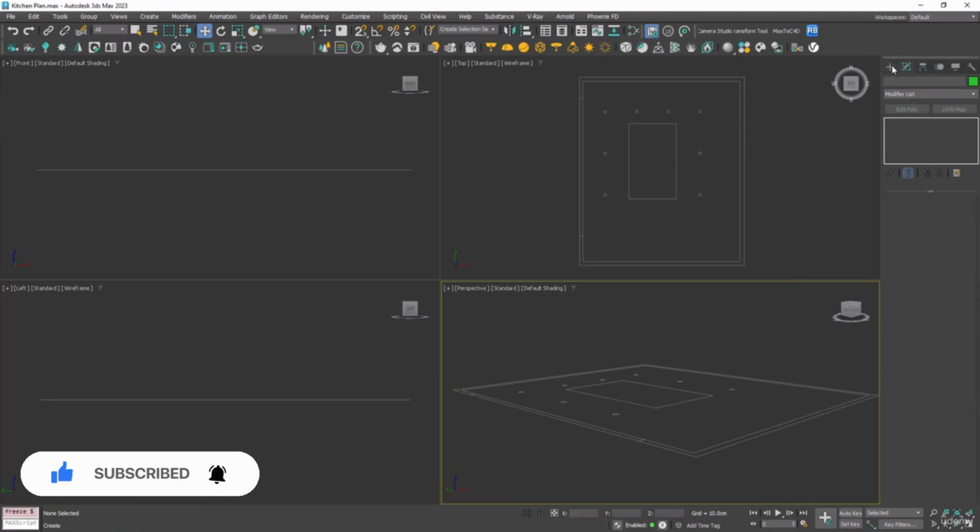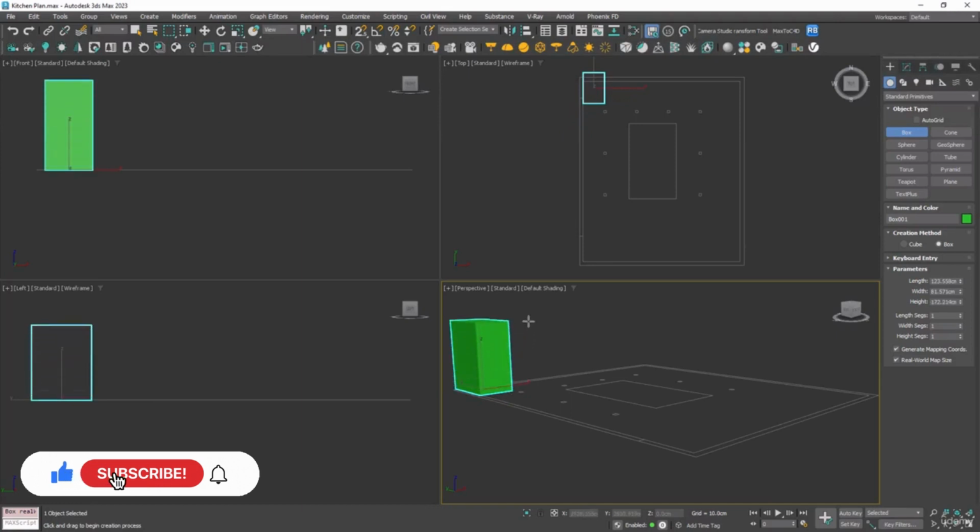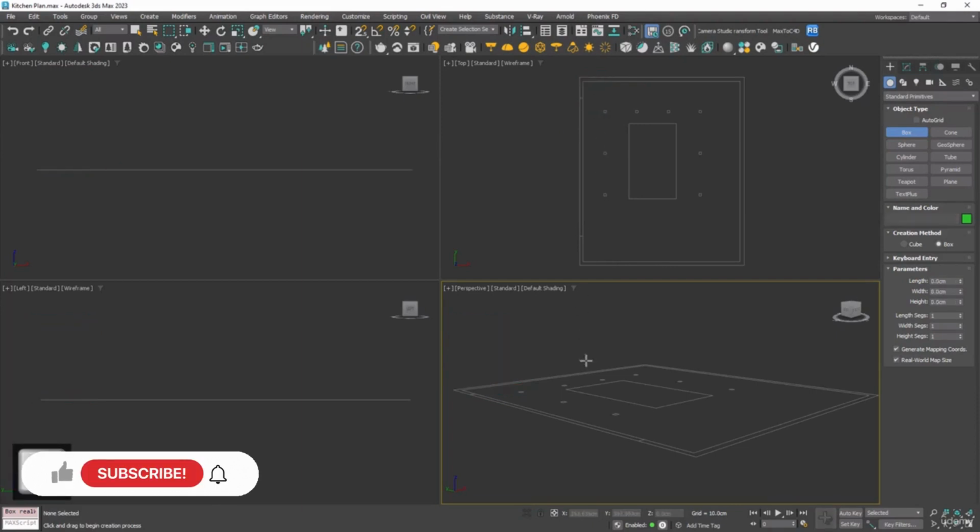So let's go to the Create tab, and we're going to create a box, and we're just going to click and drag, and we've created our first wall. But the thing is, we actually want to be snapping to our floor plans. So let's delete this box and turn on snaps. You can do this by pressing S, or you can go up here and click on the snaps toggle.